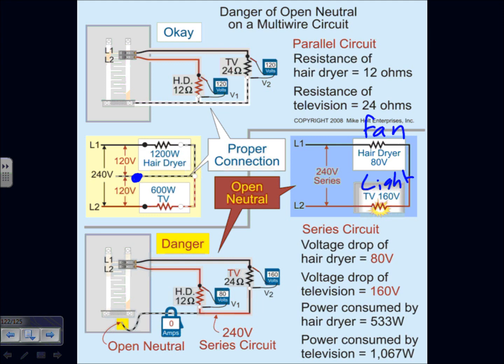It kept sucking more current to compensate for the lower voltage. That's what motors do, guys. They're dumb. Instead of saying, you don't give me enough voltage, I want to stop right now, no, they start sucking more current to compensate for the loss of voltage to maintain the same horsepower that they're supposed to deliver. What happens when you start sucking more current in the windings? They start smoking. Within seconds, a big ball of fire came from the fan in the corner.